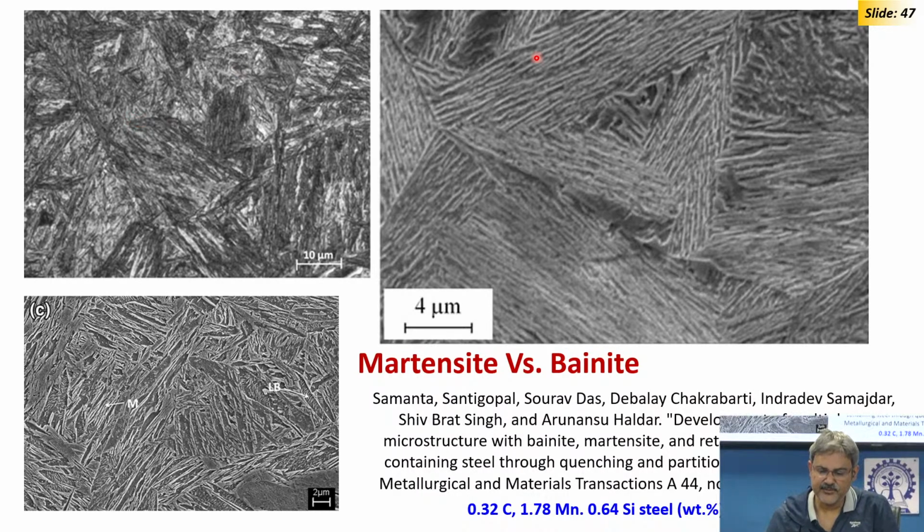In bainite you will find a long region where there will be short platelets. Here you do not see long plates. Why? Because bainite forms when austenite is more plastically deformable, softer. So, in front of a bainite plate, as it grows, a lot of strain accumulates at the interface. So, austenite gets deformed and the dislocations interact with the interfacial dislocations, you know. This is called mechanical stabilization, and it will stop the growth.